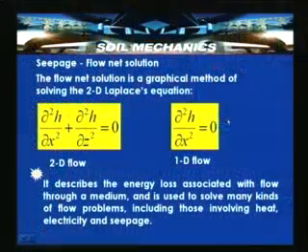So, the equation of continuity is now ∂²h/∂x² + ∂²h/∂z² = 0. In case of one dimensional flow, ∂²h/∂x² = 0. So, if the flow is taking place only along the x direction, then it is called ∂²h/∂x² = 0.